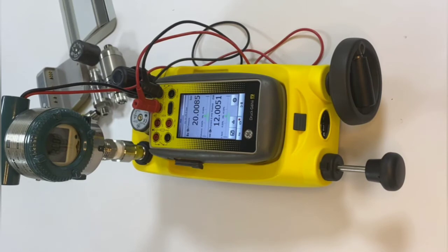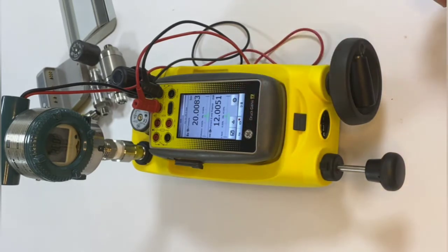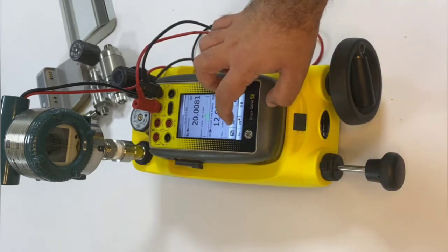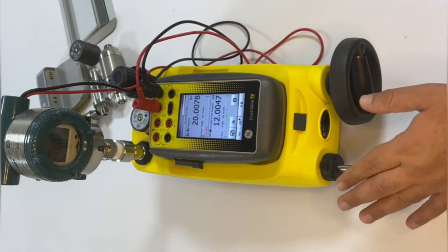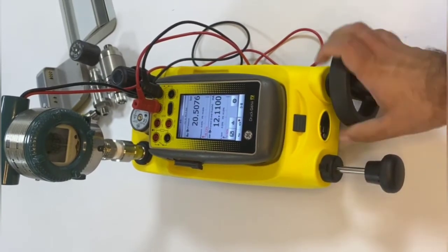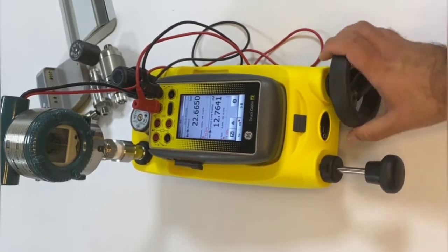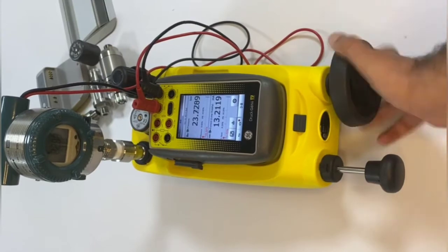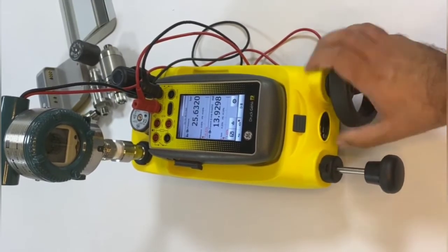and our tolerance is plus minus 0.2%. Press on this, so it will store the point. Now go to 40 bar. Now I don't have to use this, I can add more pressure simply by rotating the wheel in a faster way. So it will decrease the volume inside and add more pressure to my chamber.